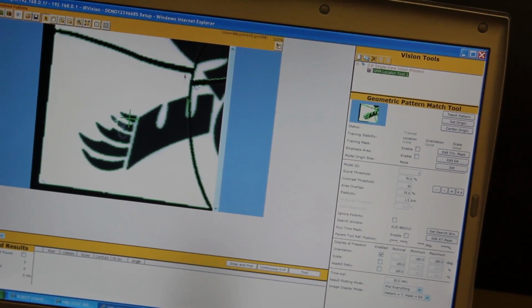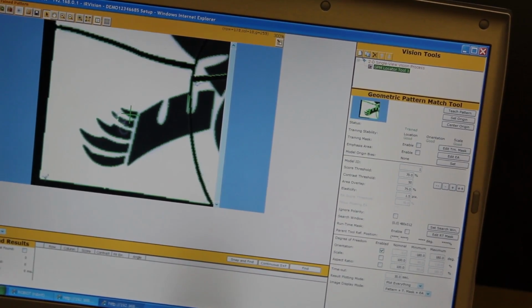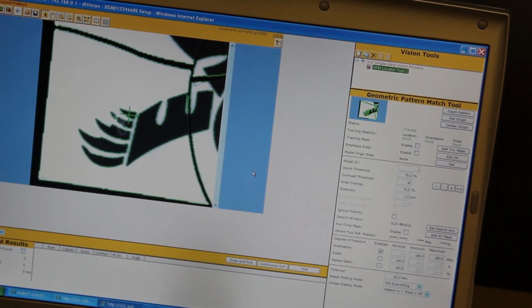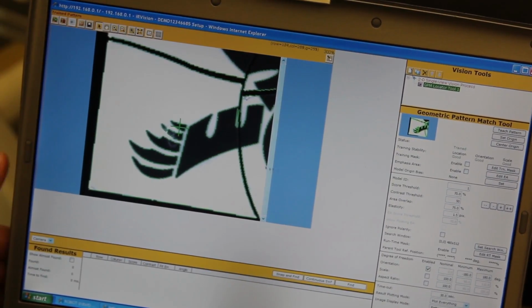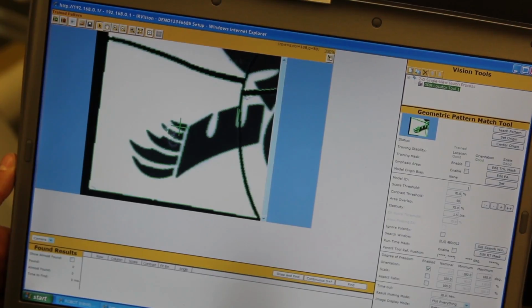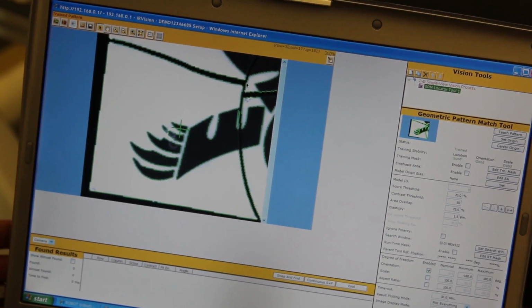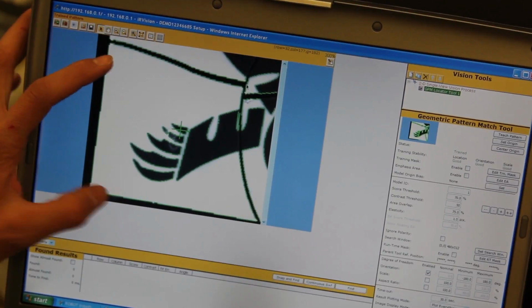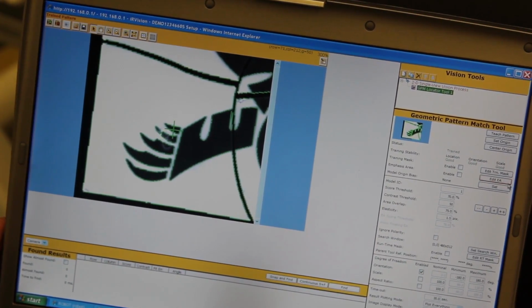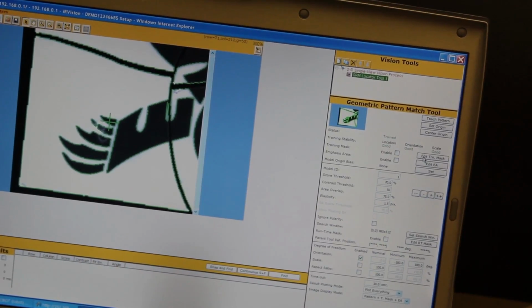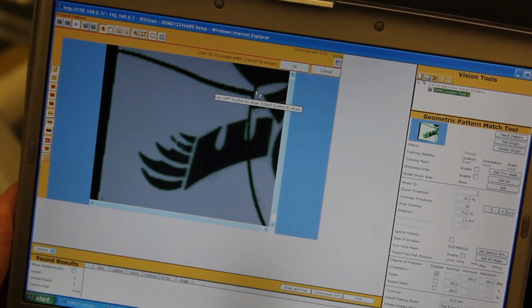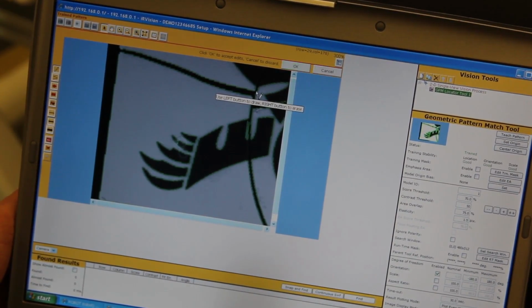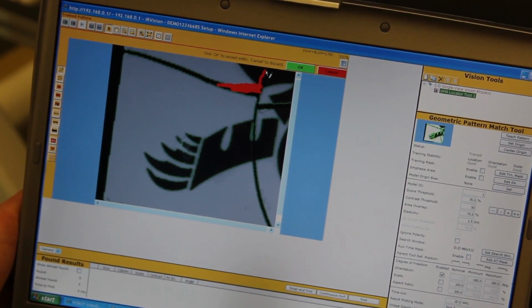These green outlines are the pieces that the robot is going to use to recognize your part. Problem is, you also have, in this example, other parts really close by that part. So you're going to have to erase all these other pieces in order for the Vision to only recognize the part that you're wanting. You'll do that by clicking over here on the right on the Edit TRN Mask. Once in there, it's kind of like Microsoft Paint, and you just simply hold on to the left mouse key and you'll just drag it along until it's all covered up,